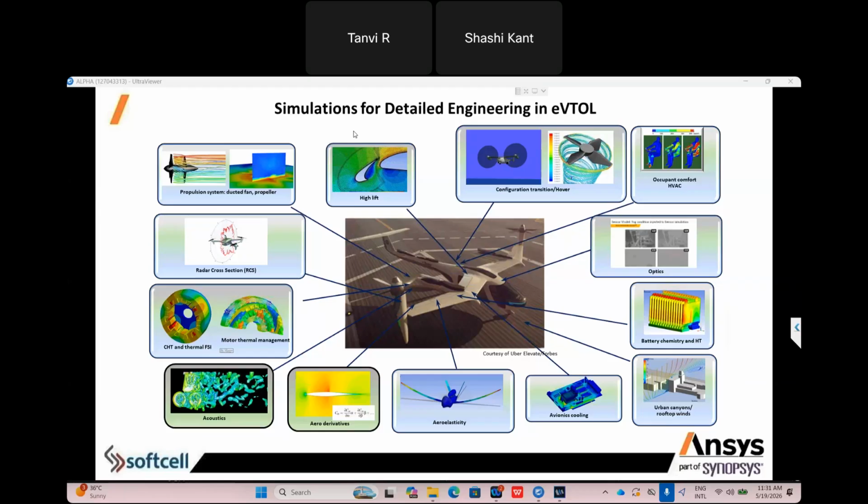You can also integrate with the outcomes. Let's suppose you want to get some specific airflow at the corner of the cabin. Let's suppose you have a corner where it is a very big problem to get air circulation properly. You can define a probe point for that location. Once you define it, you can give a limit like this: the velocity I need at this location. So the system can tell you the exact CFM required for the HVAC system for making proper cooling or air circulation inside the cabin. It can also recommend the location of the vent.